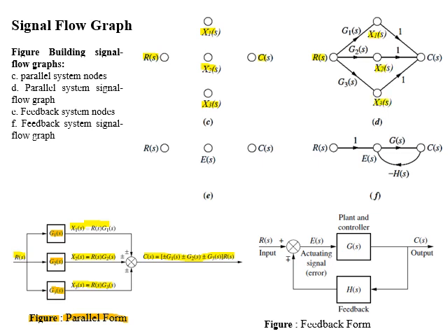Now we will make connection of these nodes as per block diagram. Node X1 of S and R of S are connected with system G1 of S, so there will be a branch with a gain of G1 of S. Node X2 of S and R of S are connected with the system G2 of S. These nodes will be connected with a branch gain of G2 of S. Similarly, X3 of S and input node R of S are connected with system G3 of S. So between these, there will be a branch with a gain of G3 of S.